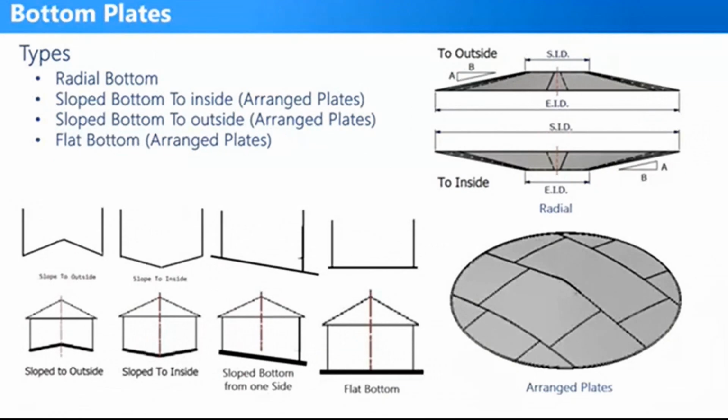You will be able to generate different types of bottom plates, like bottom sloped to outside, so the highest point will be in the middle. Sloped to inside, so the lowest point will be in the middle. Sloped bottom from one side, where the bottom will be sloped in one direction only, and the flat bottom.